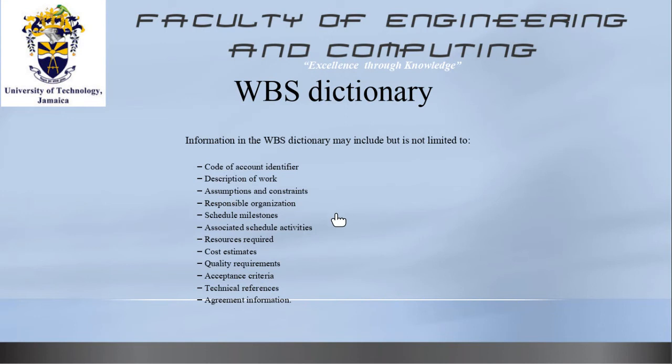The system that we are developing is a 110 volt system or a 24 volt system. Most motors of 50 hertz will be a 220 volt system, and so that's a constraint. Or we can get it, but we may have to go into Europe to get it, and it may delay delivery. Those are constraints.